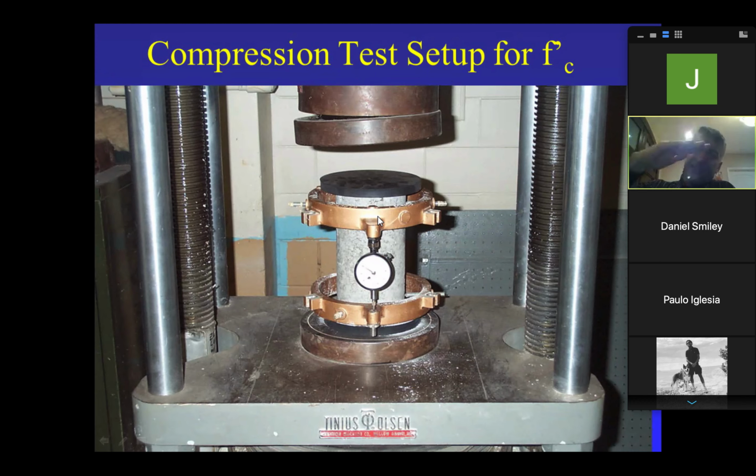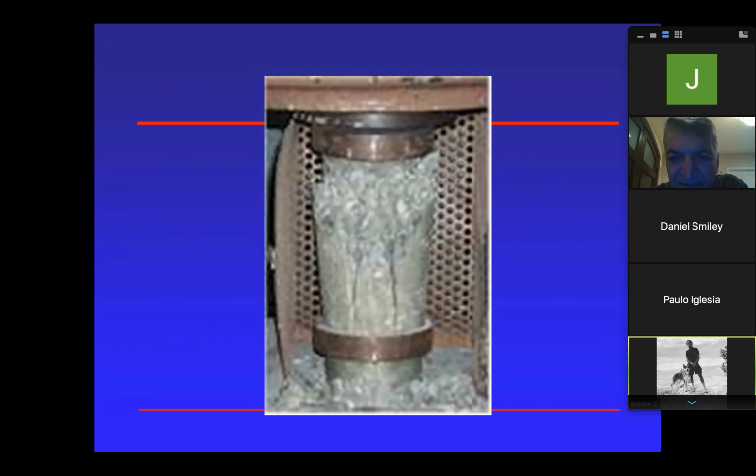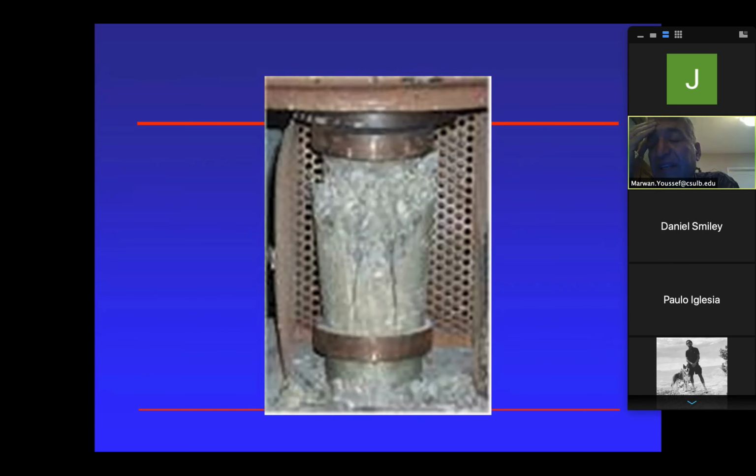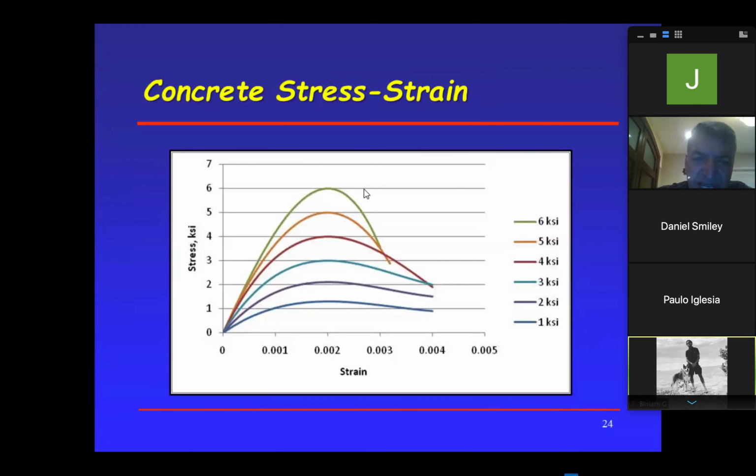So as you compress, let's say you started from zero, you press a small force, this went down. That amount that this cylinder went down divided by 12 is your strain. Then the amount is going to go down further. The new amount divided again by 12 is the strain. Change in length per length. So it's the total elongation versus the original length, I think? Yes. It's the total divided by the original. Okay. So once you do that, then you're going to get these points.